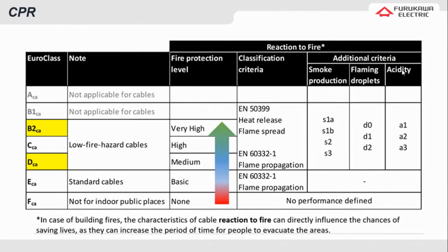Now, it's up to the designer or to the installer to satisfy themselves that the products chosen are appropriate for the application and that they meet any contractual requirements. So, whenever specifying cables, take care to assess the risk of fire within a building and the potential ease of evacuation. Each application, I don't know, a hospital, a prison, a tunnel, an airport, a building, they all offer their own unique challenges and they should be assessed individually.